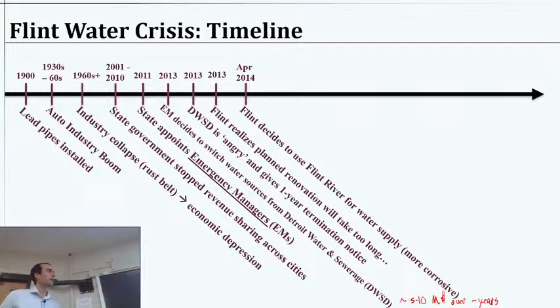Maybe it's a lower pH, maybe it's just a lack of alkalinity. It's more corrosive, and the big deal here is that we have to control for corrosion if we want our pipes to not corrode, right? So if we have more corrosive water, it's going to tend to corrode the pipes if we cross some threshold.